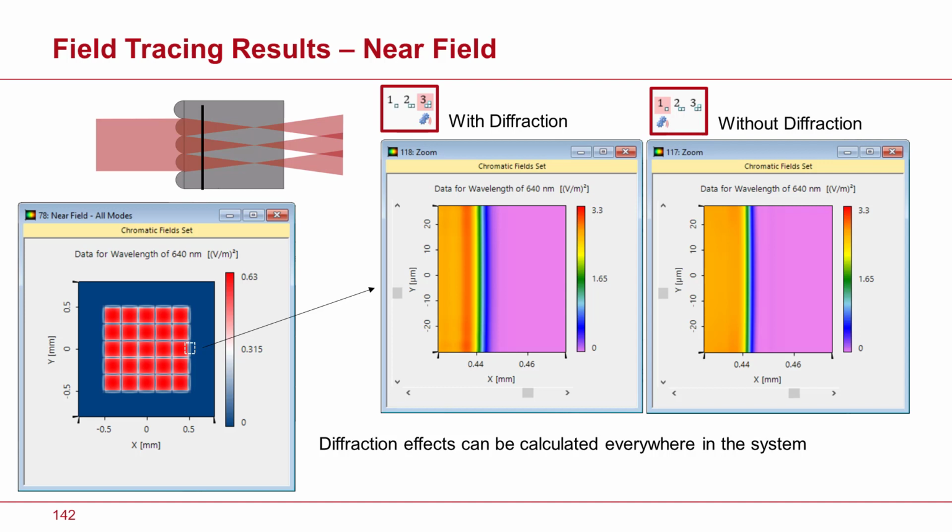And I take this chance to mention another new feature, which is the modeling levels. If you have played with VirtualLab Fusion before with the previous versions, you will have surely encountered the different Fourier transforms that we offer. And a new feature that we bring with version 2021.1 are these modeling levels, which provide default configurations of those Fourier transforms to make handling easier for those users who are not intimately familiar with the intricacies of all those Fourier transform algorithms.